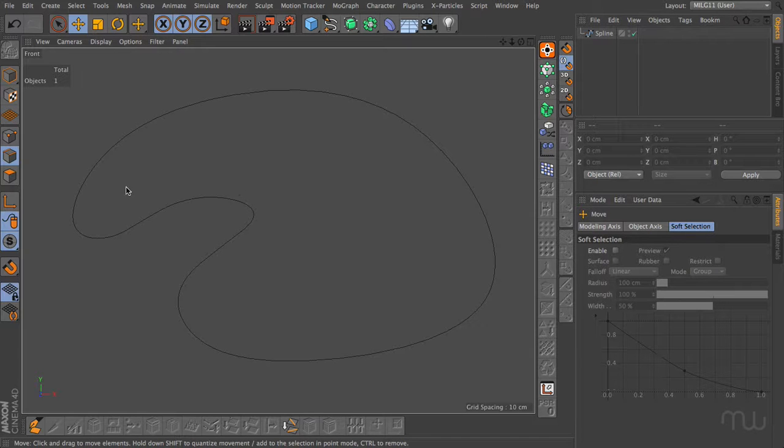So what I'm going to do is I'm going to create the topology very quickly for this shape. And we'll also have a look at how we can ensure we have a continuous edge loop so we get really nice smoothing on all of our edges using the concept of edge flow to achieve this. Now it's not going to start out like this, but I'll show you how you can resolve your edge flow at a kind of later stage in the modelling process.